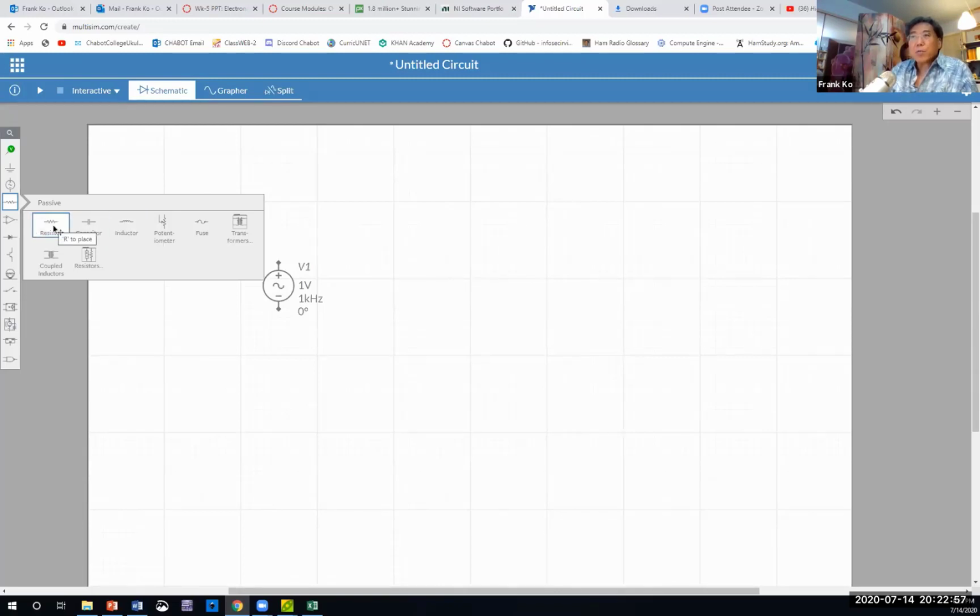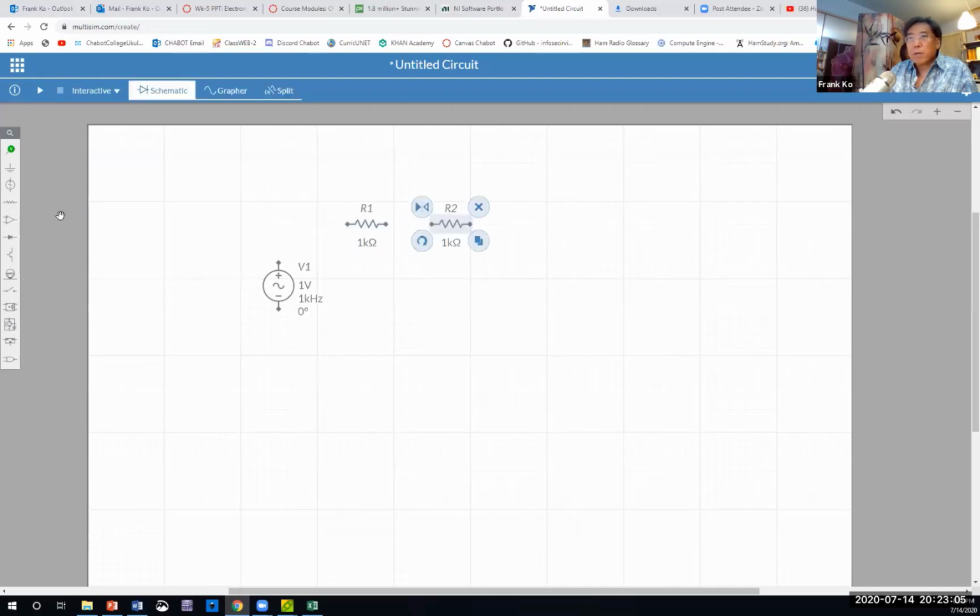So I'm going to select resistor. I'm going to click and drag and place one here. I'll come over to resistor, click and drag another one and place it over here. Click and drag another resistor and place it over here. Okay, deselect. Then I come over to schematic connectors, bring a ground, and bring it over to here. So now do I have components placed on my board in a fashion that is similar to Tina? So far, it's very, very similar to Tina. Just give these some spacing apart.